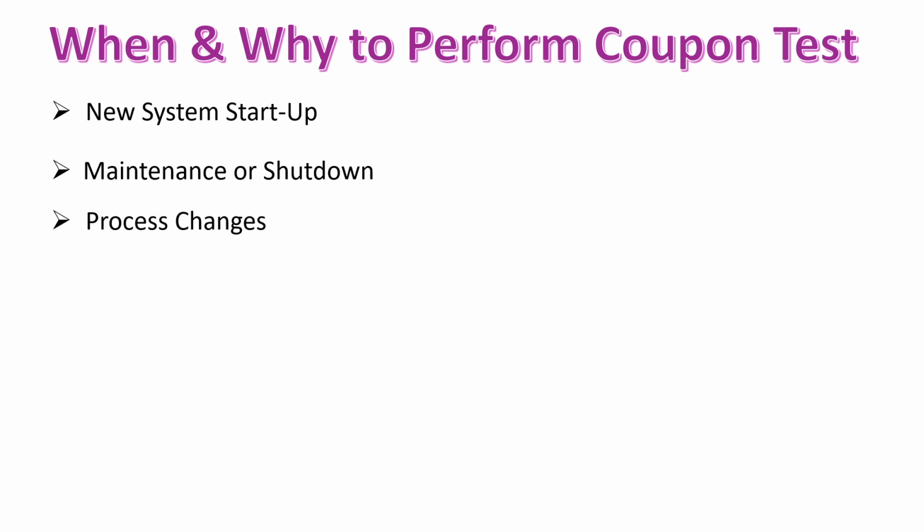Then third is whenever we are going for any new process, using the existing setup for a new process, where there is a change in process or any operating conditions. The corrosion coupons may be installed to monitor its impact on the corrosion rate and identify potential issues.